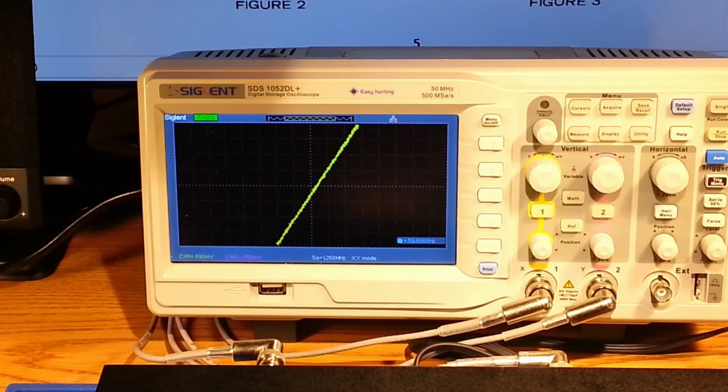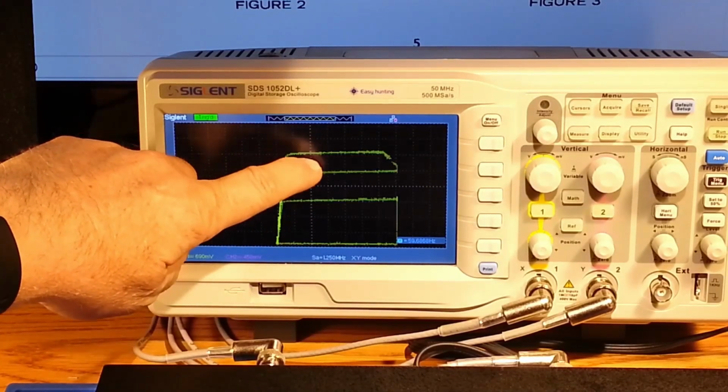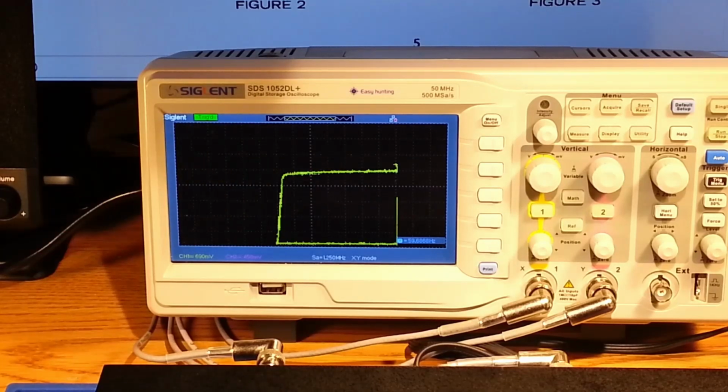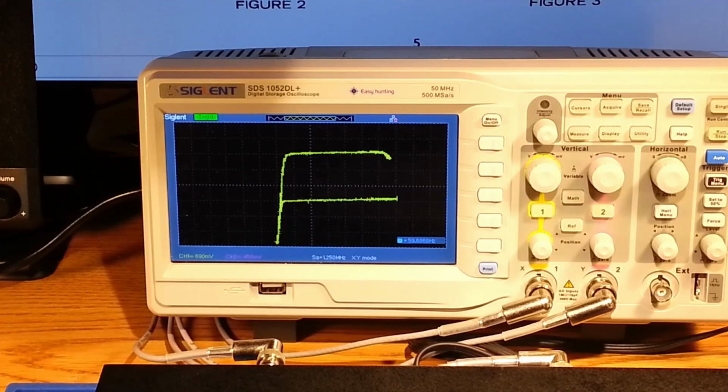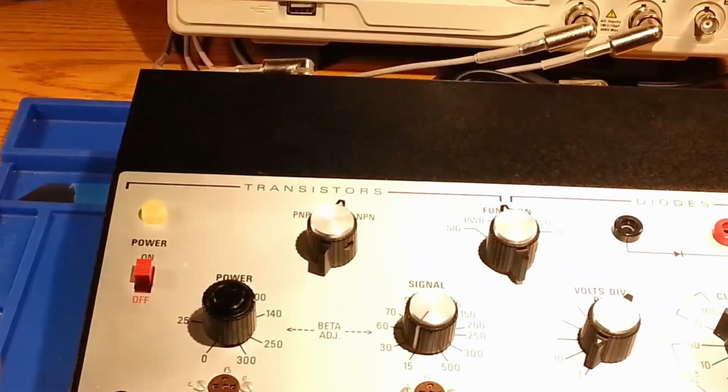I don't know how the horizontal position is going to work, but I'm going to click this guy back in, and if you notice there is 1, 2, 3, and 4. There's 2 of them tight going back and forth, and they're not progressive because of the manner of the stair step signal design on this. I think I showed you earlier. It's not a progressive step up in voltage. The steps kind of alternate levels in a weird progression, but you don't notice it as much on an analog scope.